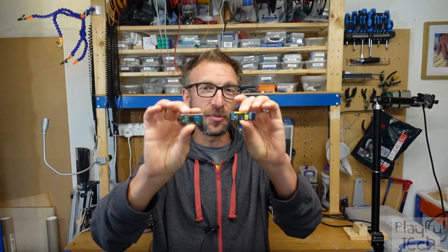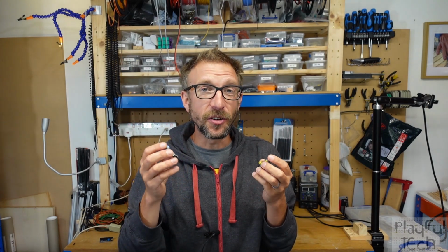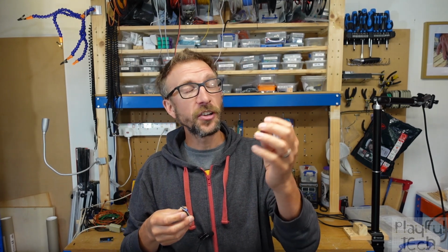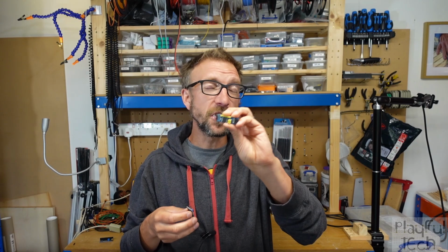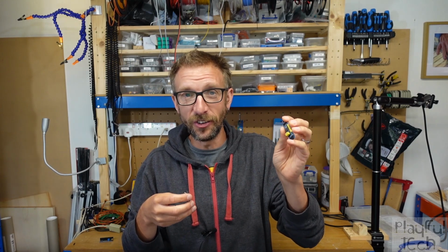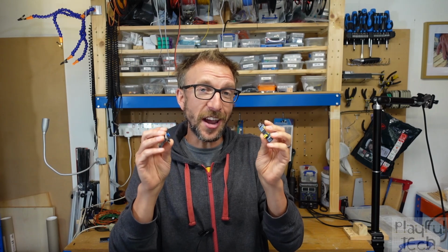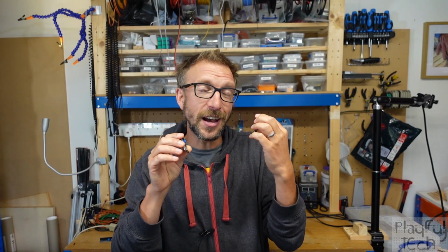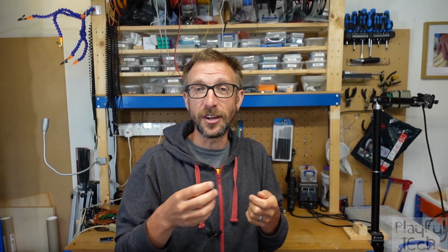So port expanders like these PCF8574 chips are great. You can buy them in convenient ready-made boards that slot onto the back of an LCD display, or with just a generic row of pin headers so you can connect them to any input or output you want. You can daisy chain up to 8 of them together to get literally hundreds of GPIO inputs and outputs. And they can operate at 3.3 volt or 5 volt logic, which means that you can use them with pretty much any controller so long as it has an I2C interface. And then they only use up 2 pins to do so.